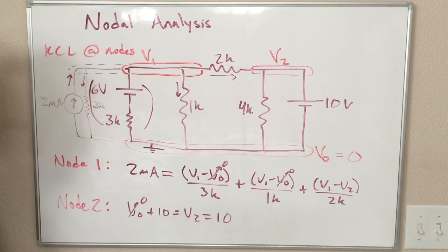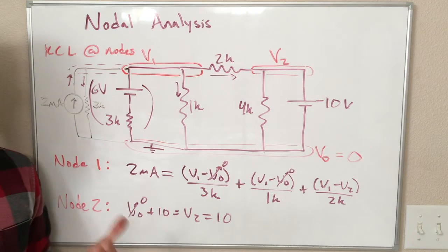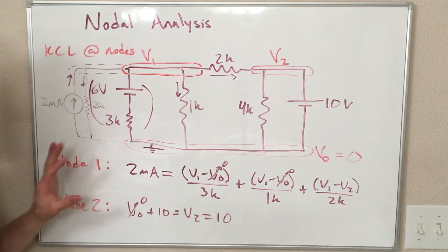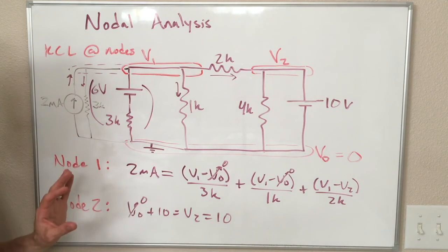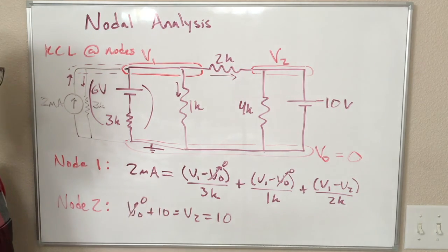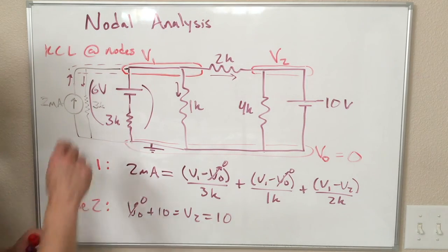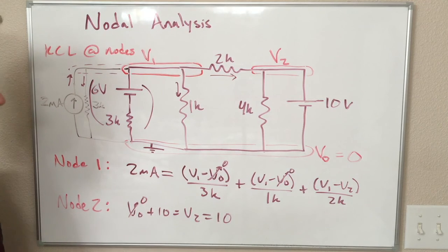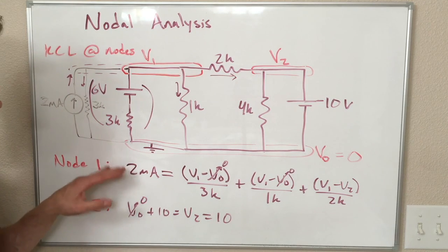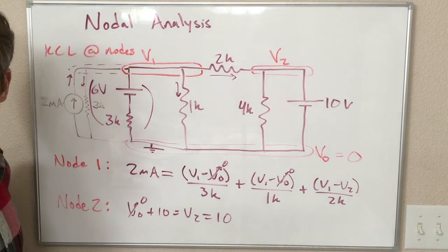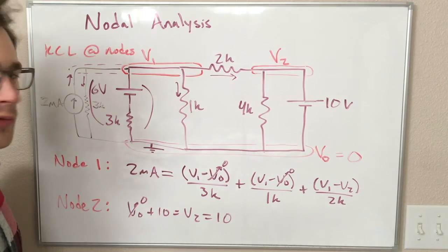It can help to get comfortable with these. Nodal analysis in particular is important because this is basically how SPICE works, the simulation software we're using. You draw your circuit, it identifies these nodes in the circuit, and it has some set of equations that it solves for the voltages to get your answer for the operating point.